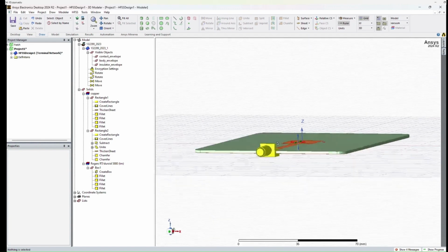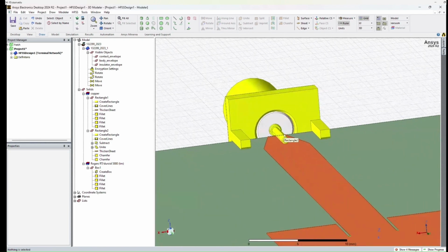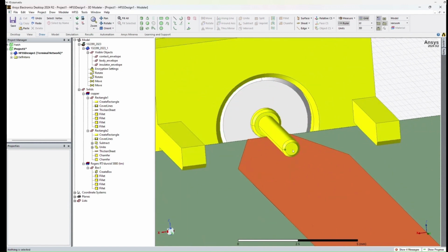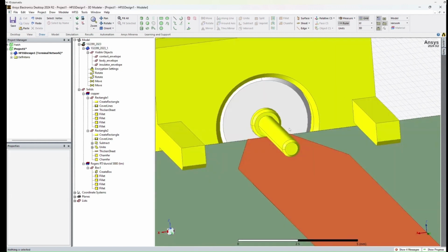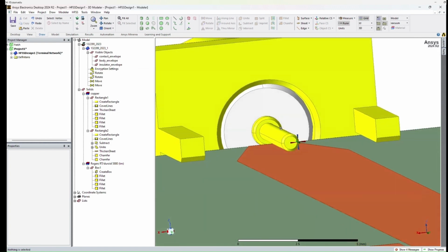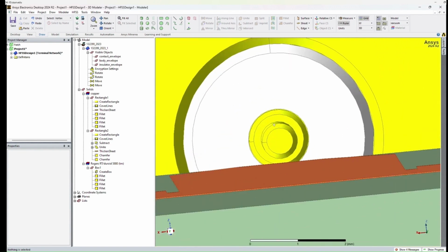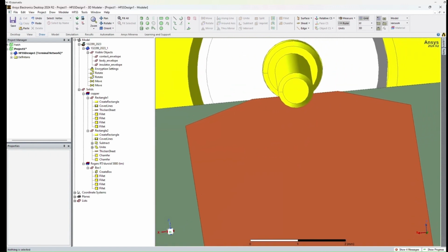So when it comes to adding solder and subtracting objects with encrypted models like this connector, we can't exactly use it as a tool, because if we just add, let's say, a box that surrounds this pin, it'll be intersecting and there'll be an error, so we'll need to subtract it. And usually that's okay. If we have two intersecting objects, we can subtract one from the other and create a space, but you can't do that with models like this connector because they're encrypted, because they're proprietary to the company that developed them. So what we'll have to do is create our own envelope of this pin around it, and then use that to subtract away from our solder box. So it won't be too difficult.